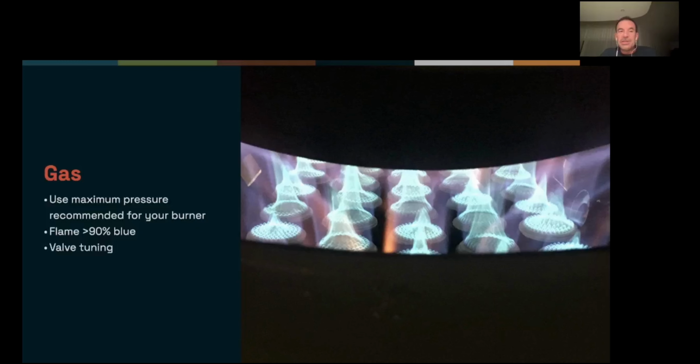There's also a separate thing called valve tuning. Some of the more modern fuel injection burners are integrated with the control panel on your machine, and it's possible that you don't have access to the top end or bottom end of your burner's potential settings. And if you ask for the valve tuning PDF in those situations, you can, for instance, get access to slightly more precision at the low end of the burner settings, or a little bit more power at the high end.